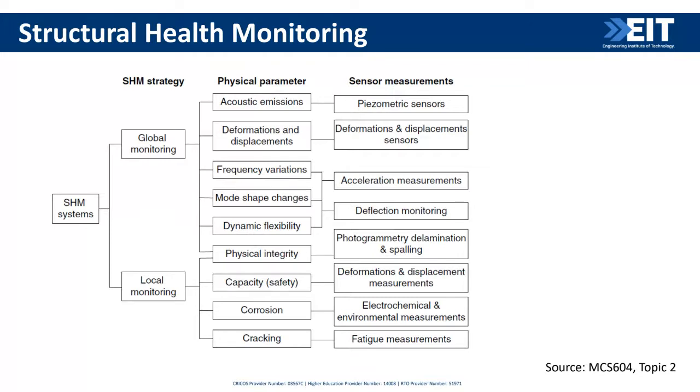And normally we can use accelerometers, where the main idea is to obtain information on the dynamic response, when the structures naturally, can you imagine, breathe, and are subject to ambient vibration. Local monitoring is more specific, as the name says, as you can obtain information in relation to cracking or fatigue, so we can collect some local material and geometric properties.